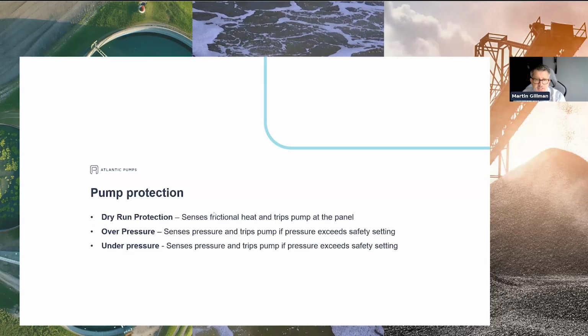So dry run protection will sense that increase in heat. It uses a thermistor sensor in the stator of the pump, and it should trip your pump out. So make sure you ask for that if you think that's a risk. Overpressure, self-explanatory. PD pumps will continue to generate pressure until something gives. Always have overpressure protection on a PD pump.